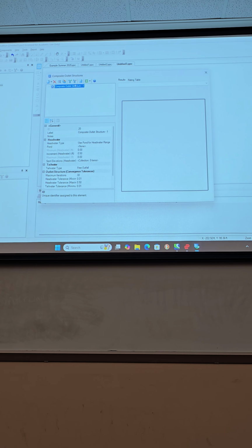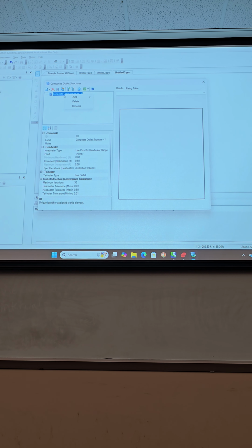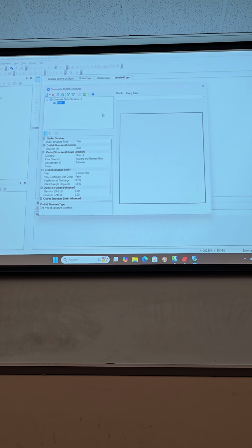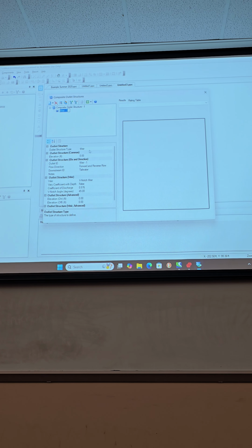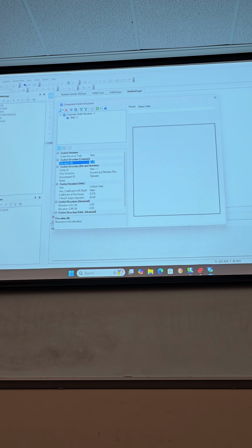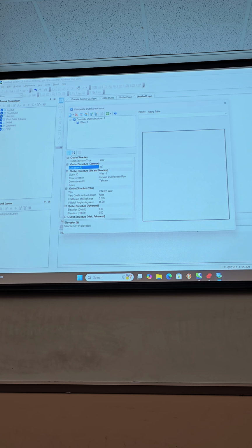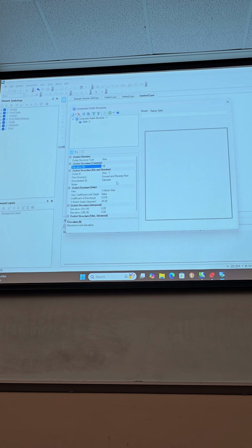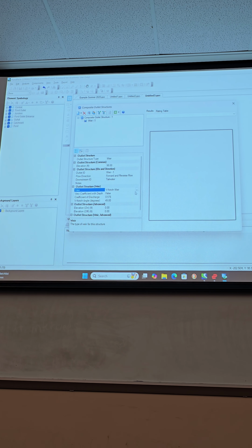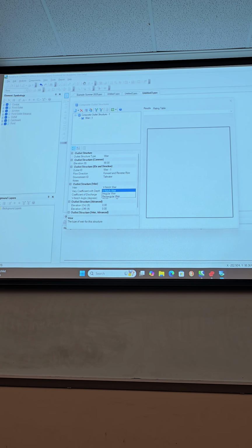but we're going to do a weir and an orifice. So for that, if I right click under add, I'm going to add a weir, okay? So the weir is going to ask for a few things. Elevation. So what's the elevation of my weir? Let's say it's elevation 98. And then it's going to come down here, and I need to define the shape. So I'm going to say it's a rectangular weir.